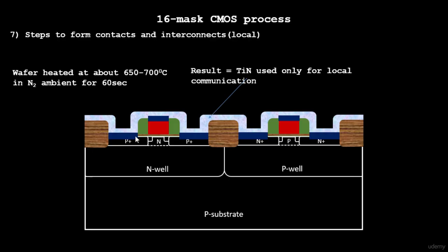So a thin screen oxide is added to avoid channeling during implants. It will help to randomize the direction of the implantation, and the ions will settle down in the areas that we want them to settle.